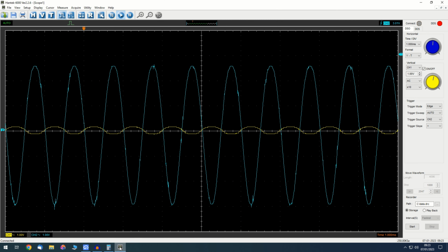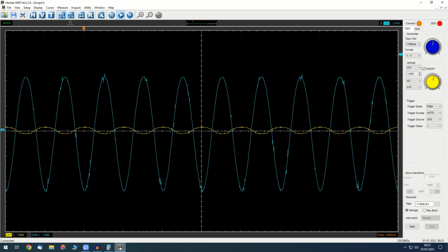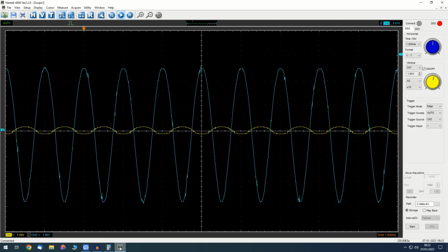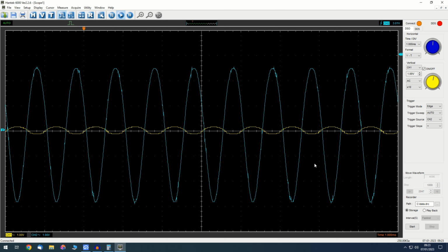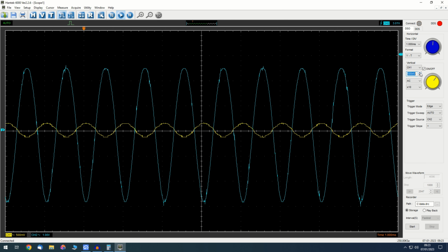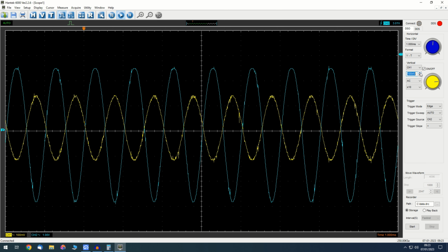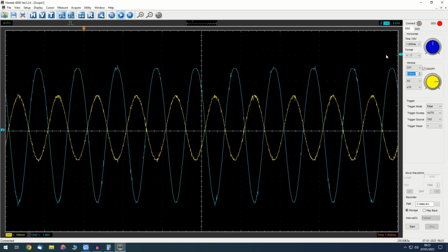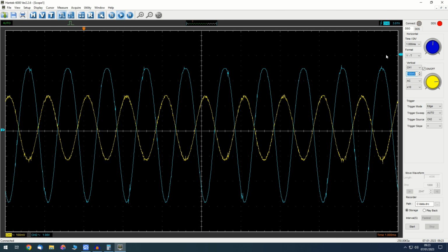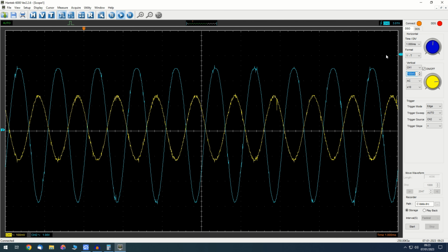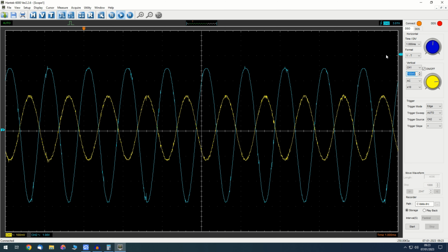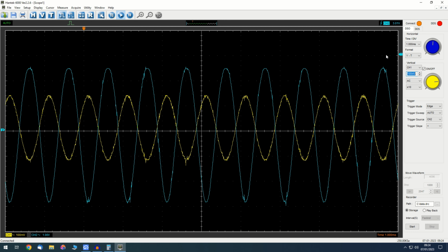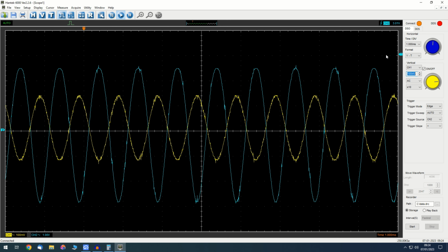Okay, so that's with a 100 ohm resistor. You see the gain is now massively higher. I have to change the channel 1 gain a bit, I think. Right, that's now 100 millivolt range on the input to 1 volt on the output. So yeah, the gain is over 20 there. You can see it's twice as big and a 10 times difference in scaling. So the gain is well over 20 at that.